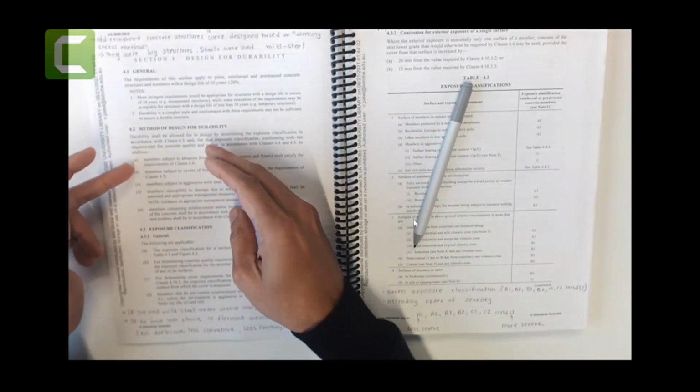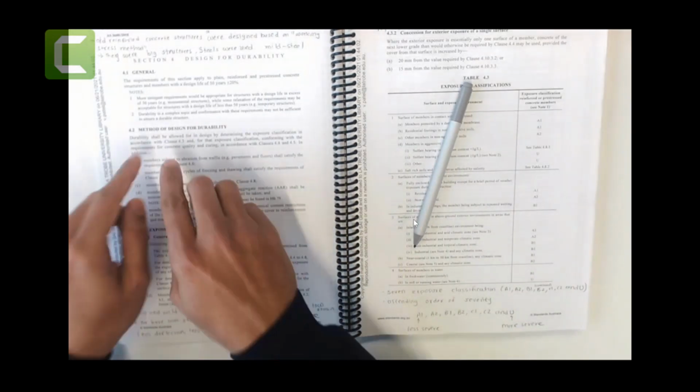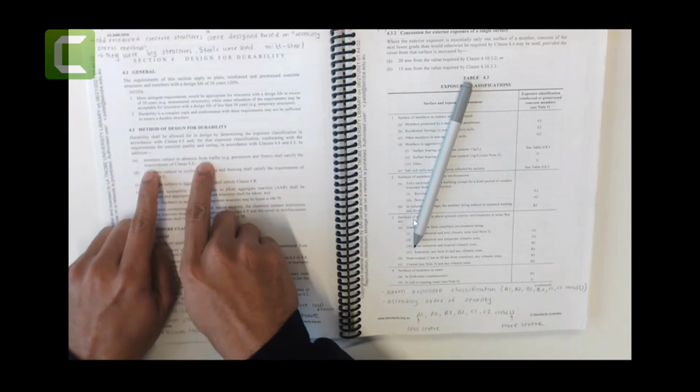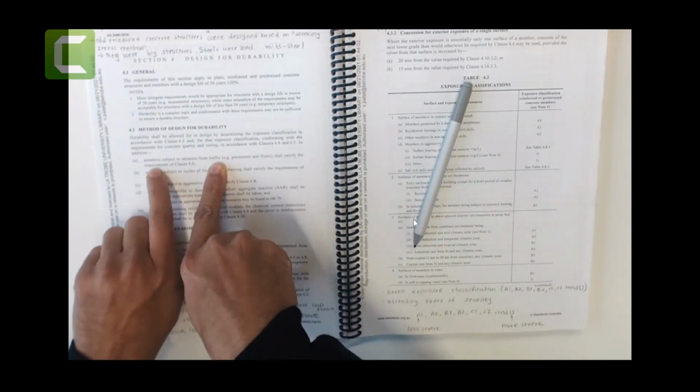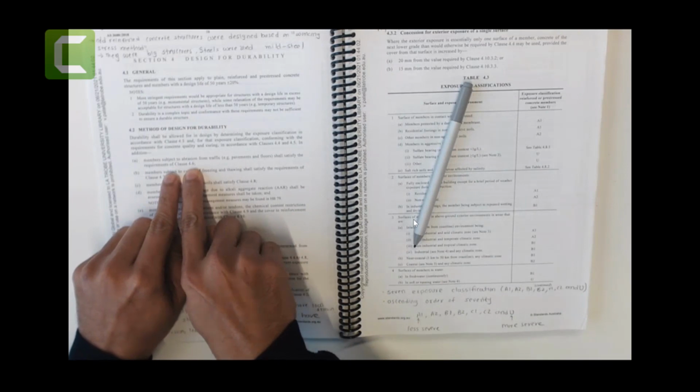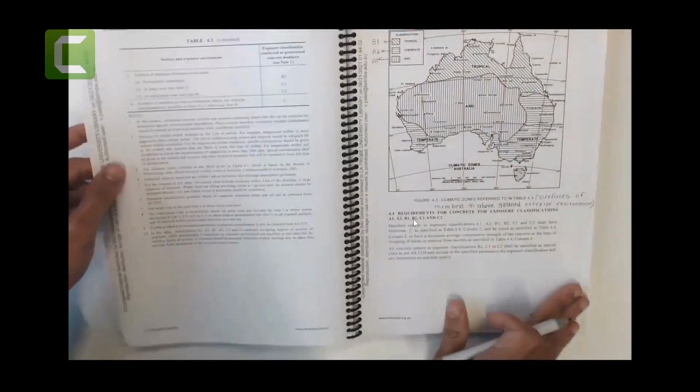Now, the method of designing for durability. There are steps given to you that you can clearly follow, so you don't need to remember them when you are designing for durability. The first step is to find abrasion from traffic. You check whether your slabs, beams, columns, your structures, the concrete, will have abrasion from traffic under clause 4.6. So if I go to clause 4.6 for completeness,